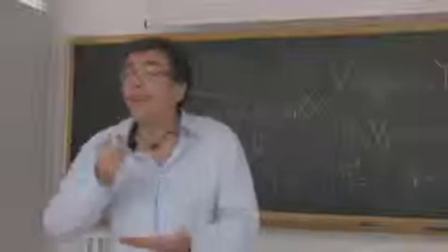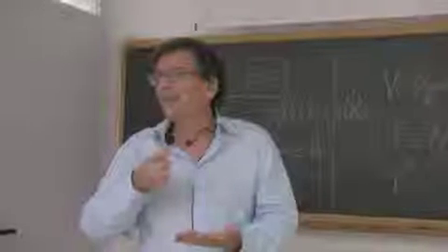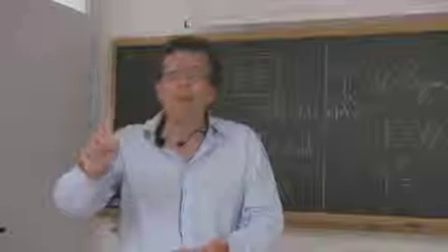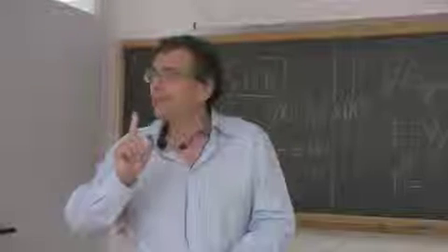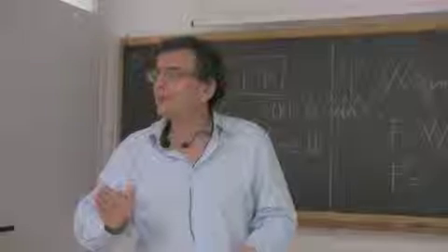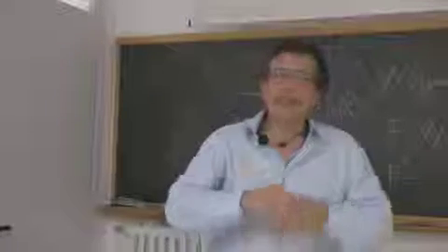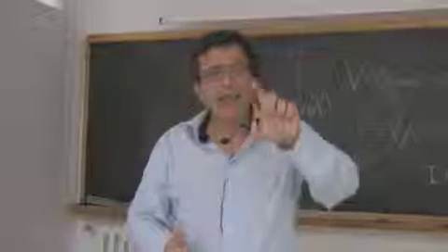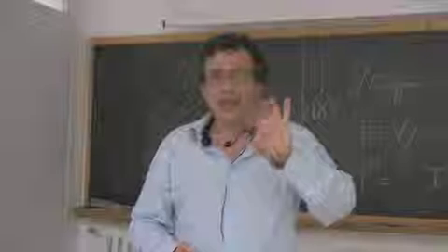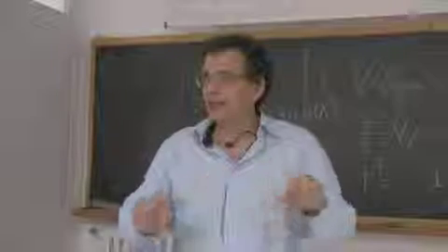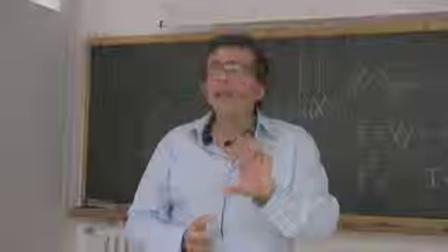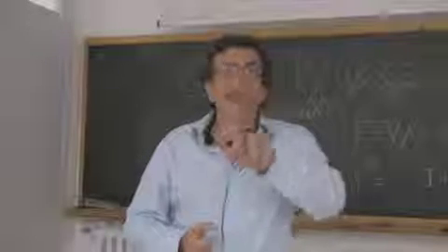So he was finding constitutive equations depending on one parameter only. So no Poisson effect. In Navier theory, you pull a material and the section in the transversal direction of the elongation can be deformed in a unique way.